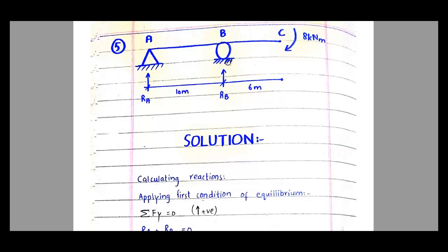not in the case of a beam that has a hinge support and roller support, because these supports cannot generate a reactive moment. So whatever load is applied, whether it's a force or a moment, will be resisted by the moments of the reactions in the form of forces. So just by looking at this problem, assuming the reactions to be equal to 0 is not correct.